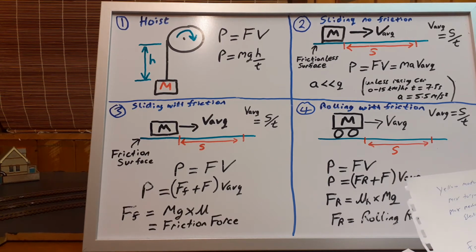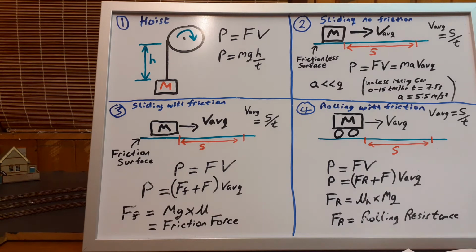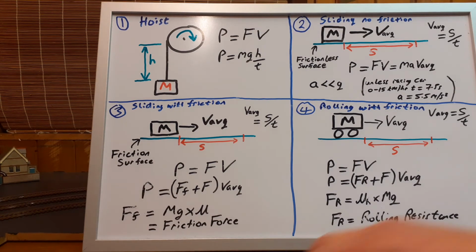Its max torque I got out of it was 0.0147 Newton meters, or 149 grams per centimeter, or 150 grams per centimeter. They're often spec'd this way. They tell you what the grams per centimeter is, as opposed to actually doing it in SI units. So you might find that for smaller ones. They're the tests I did on that. Okay, so that's minimal, as we say, and it's not correct.